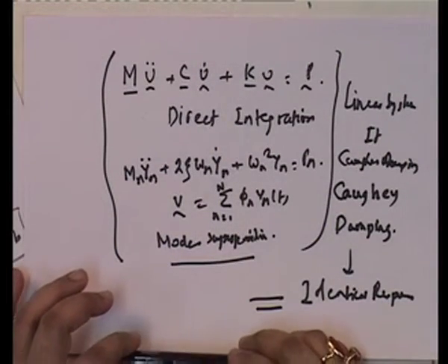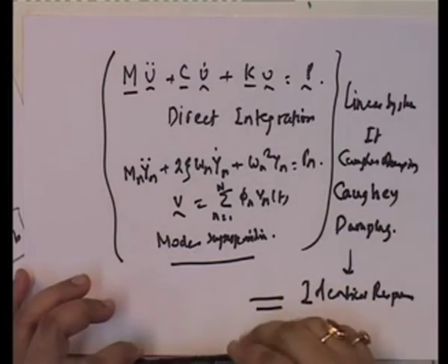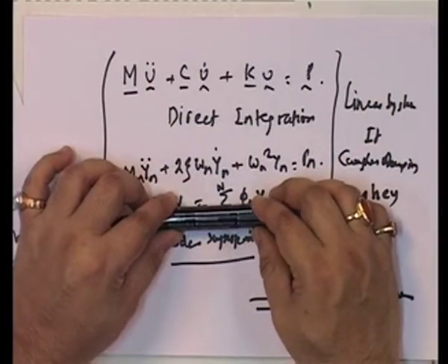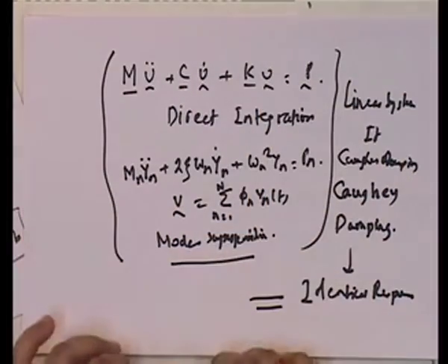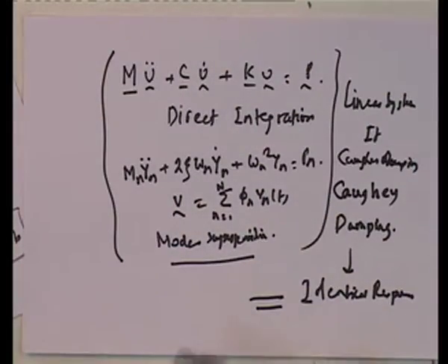If you use stiffness proportional, you overestimate the damping, and so you underestimate the response. So, this one is going to be lower than this. Okay? And if you use Rayleigh damping, it becomes a little bit more complicated, but this one and this one are definitely not going to give you the same result, and so only Cauchy damping will give you the same result. Please understand that.